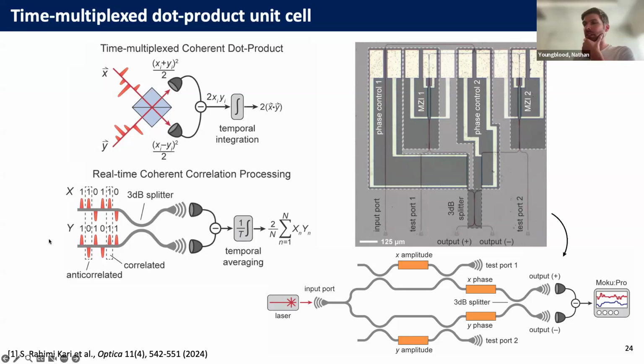Yeah, that's an excellent question. The answer is you want a laser source that is fiber coupled to your input, and then fan that out to every single modulator. So everything is on chip. As long as you can control the temperature on chip pretty uniformly, you don't have to worry about that, because the entire thing is on a heat sink, and it's all referenced to the same input waveguide.